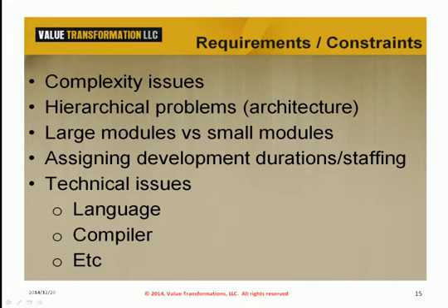Consider the calculation for serial failure modes. This is the probability of each failure mode times the probability of the next failure mode. As we increase components, we significantly decrease the reliability of the product. This calculation is equivalent to Six Sigma rolled throughput yield.